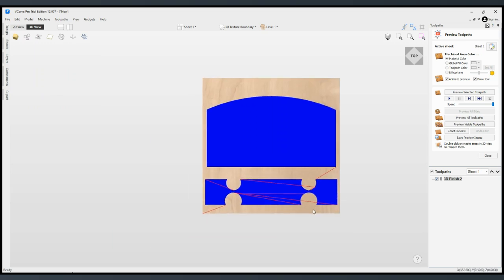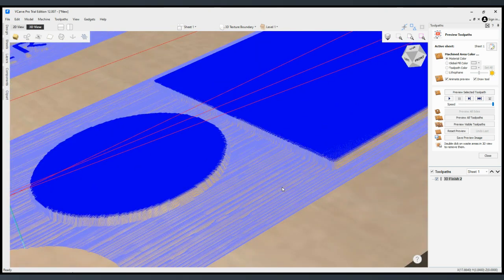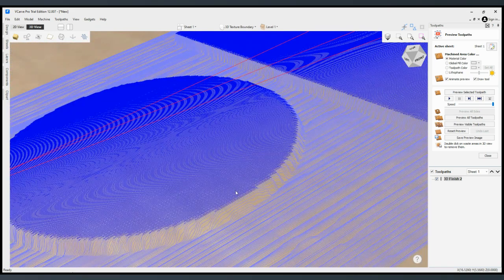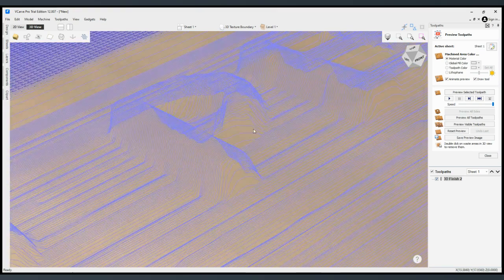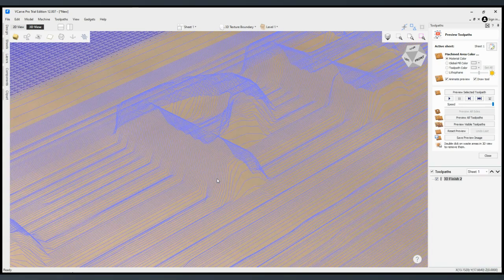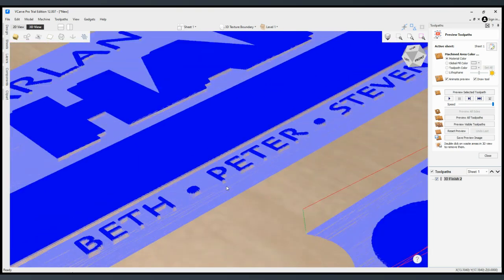You can see, based on the vectors that contain the toolpath, it only cut inside of an area. You noticed how where I didn't select the boundary, it went over the top of it. If we want to restrict it and say don't cut inside of those areas, we can remove that. The other thing you'll notice is that the letters are part of the embossment, so you can see how they are 3D cut into the sign with the texture.